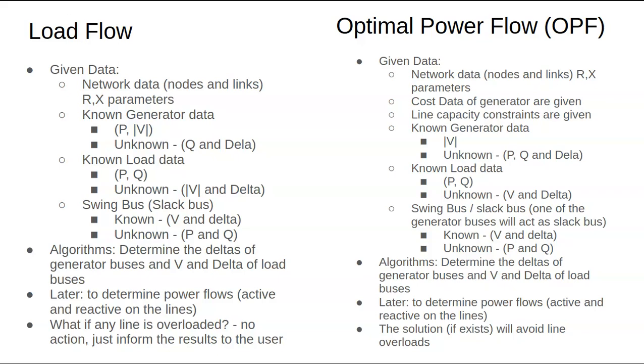So then you go to load flow, set the number 400 there, and then run the load flow and see what happens. Yes, so your cost may increase. It may happen that the generator which was saying 250, not because of the generator but because of some other line getting overloaded, has to reduce its generation capacity.